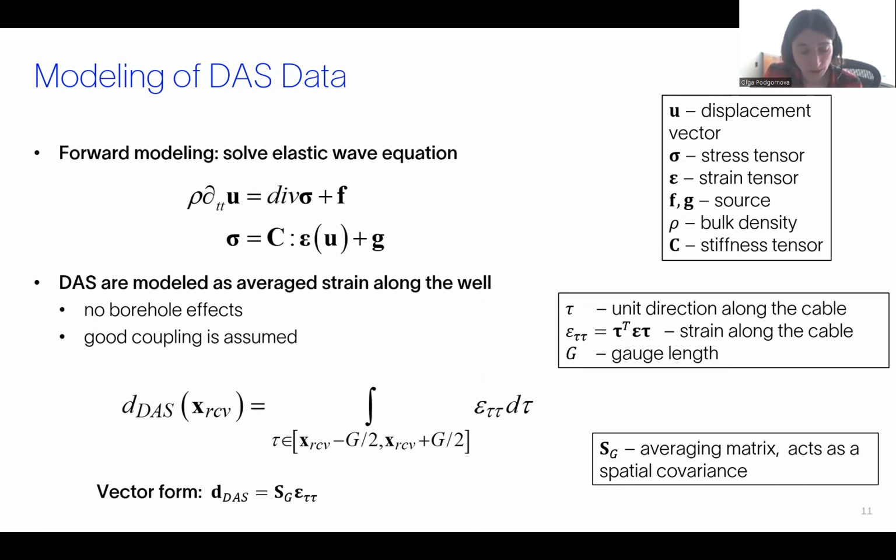Second, by trying to invert this as it is, we actually got a quite decent result. I'm not saying that it's perfect, but it gives a confirmation that the amplitude is not so bad, and can be used in data of good quality. And also, what we have in mind to work on is introducing a certain transfer function for the receiver side, which in the simplest way can be just a scaling factor at a certain depth position to compensate for the variations of the amplitude, maybe due to imperfect coupling.